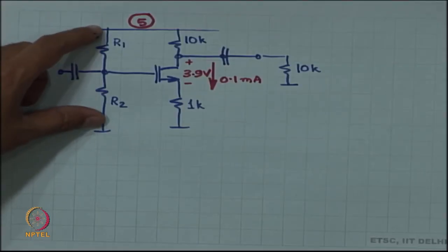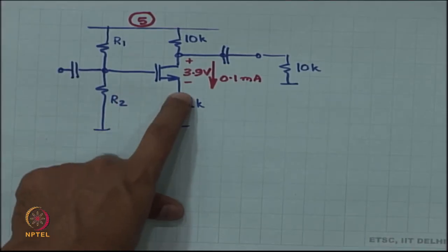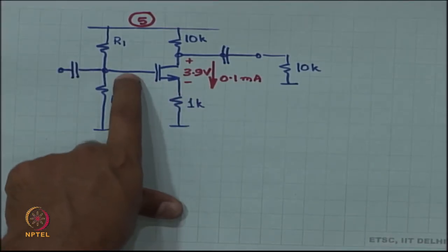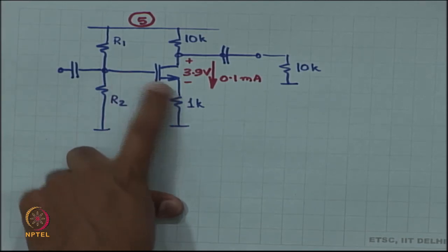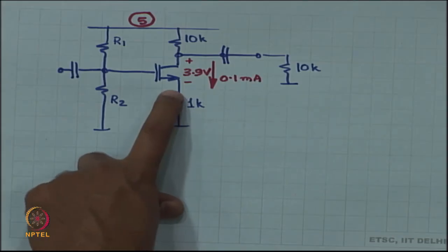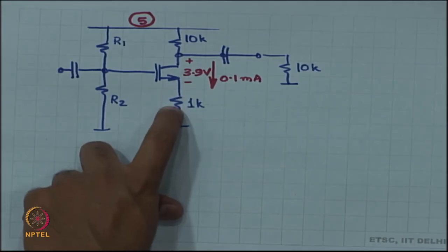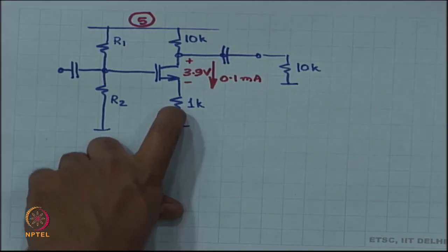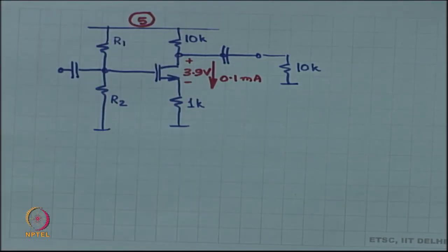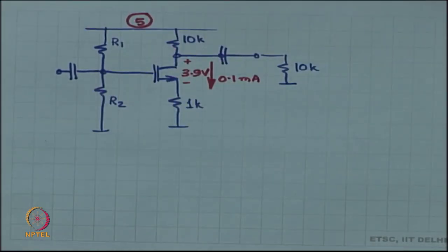You say that the voltage at the source over here is going to be pretty much equal to the voltage at the gate. So, if I apply Vin at the gate, then the voltage at the source is also almost equal to Vin. So, the current through the source resistor is Vin by 1 K, Vin by the source resistance. This current has to come from the top. Now, from the top means you lump these two resistors together, right. Obviously, it is going to split up between those two resistors.